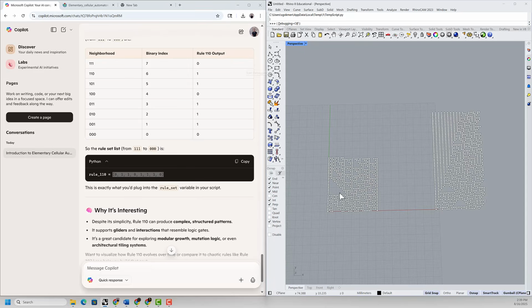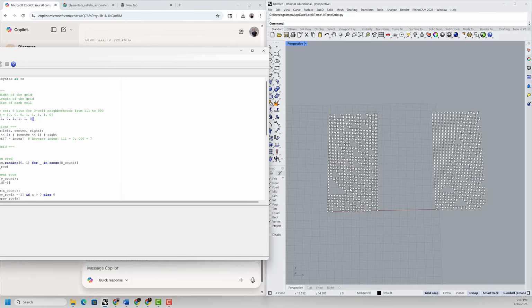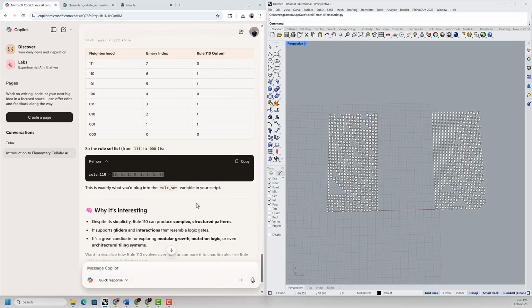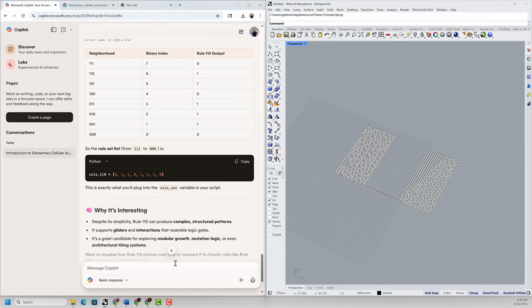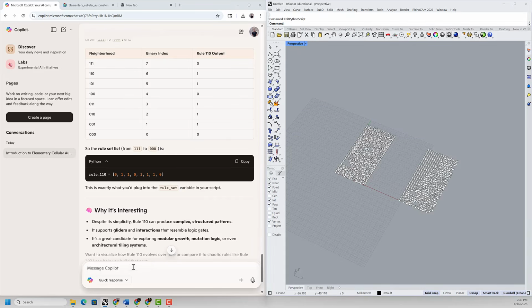All right, this might take a while, but you can see my triangles, or the triangulation, is kind of rotated in this version. So it was, the hypotenuse was facing the x-axis, but now it's facing the y-axis here, right? So we can basically plot different variations like this. Now we can of course run it in Rhino as code, but what if we want to build this as a tool in Grasshopper?